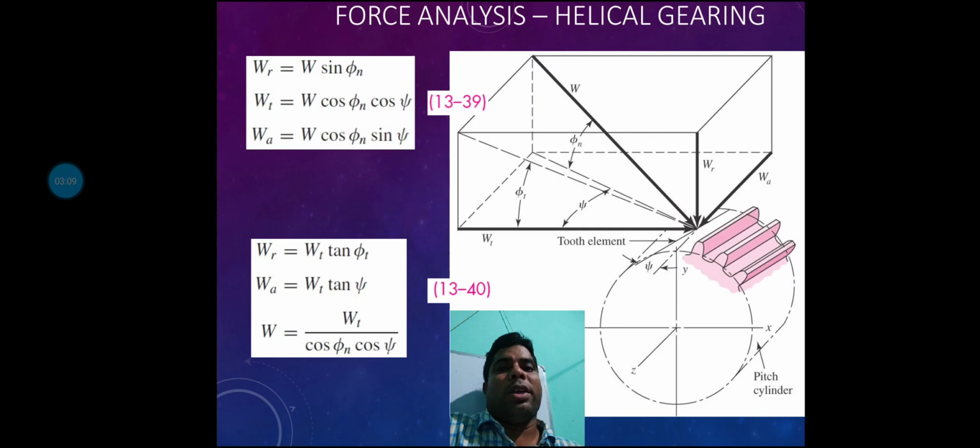And if I apply a load, suppose you see the figure, that load W is applied tangentially. Suppose an alpha angle is also there, and that alpha angle is called the helix angle. So W is the total applied load at a certain angle, and the tangential load will be WT, and the load acting radially is WR, with some assumptions.